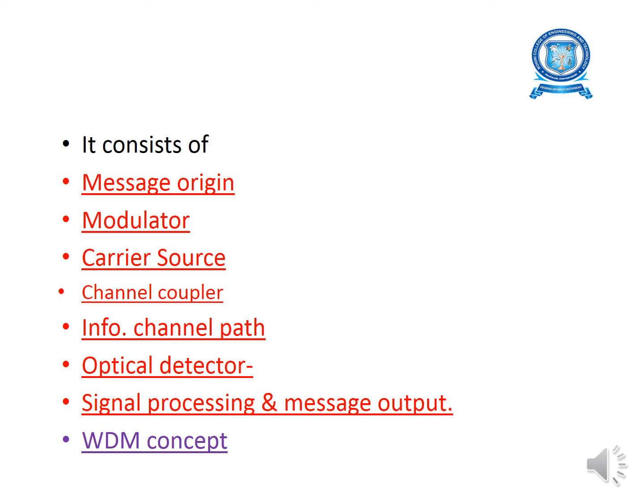The optical detector output current contains the transmitted information. As the optical detector, we use a photodiode, which may be an avalanche photodiode, a PIN photodiode or a PN junction diode. Phototransistors and photoconductors are also utilized for the detection of signals as optical to electrical conversion. The electrical signal is then amplified and restored to its original form with digital signal processing and prepared to pass on the original information.